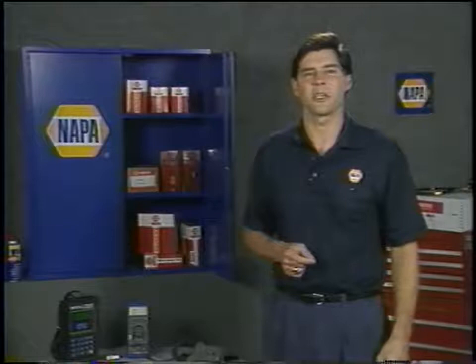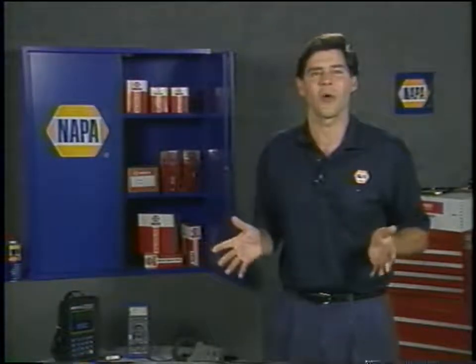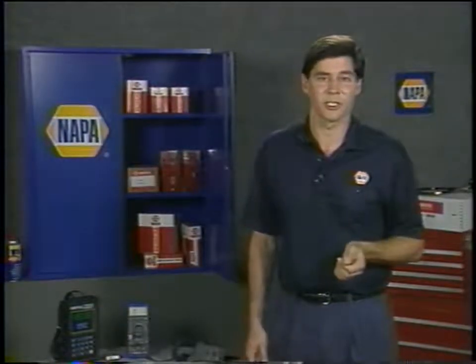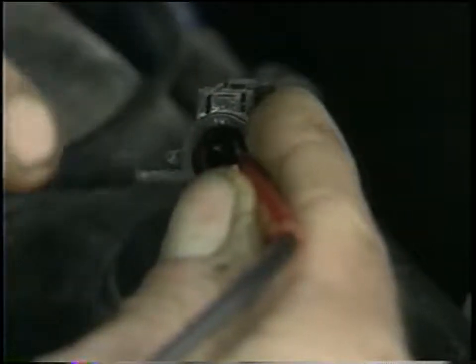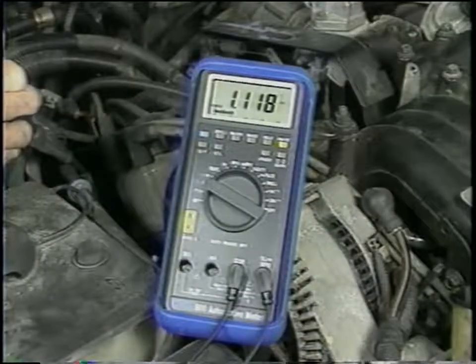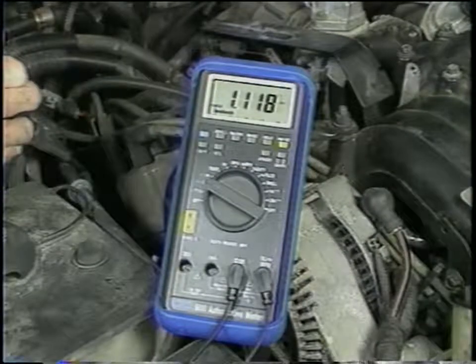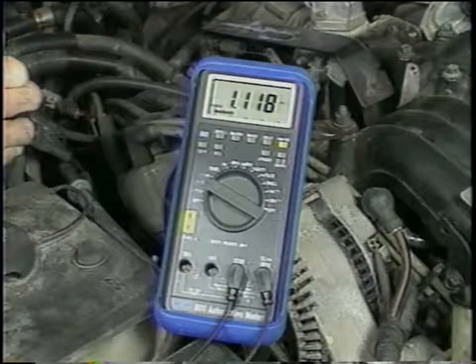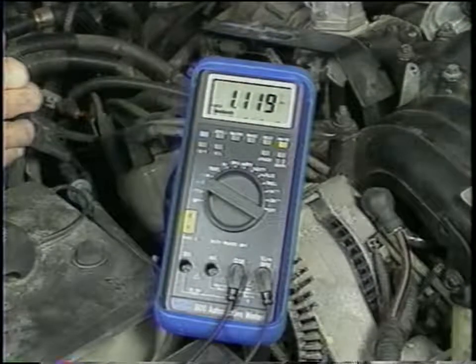Since many common ABS faults are electrical problems, such as shorts, opens, grounds, loss of voltage, excessive resistance, and so on, this segment deals with electrical test procedures that are often necessary to pinpoint what's causing the problem. A digital volt-ohm meter is an essential piece of test equipment that can help you measure circuit voltages and resistance and check continuity. A digital volt-ohm meter is better than a test light, because it gives exact voltage and resistance readings, not just an indication of whether or not voltage or continuity is present.